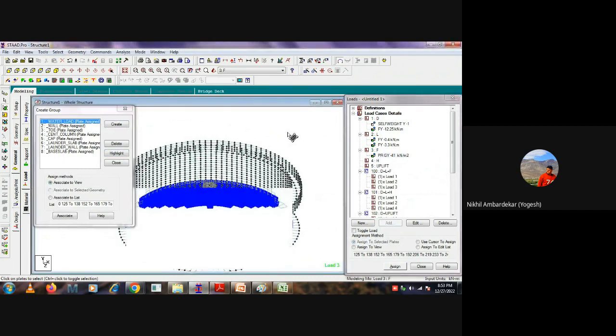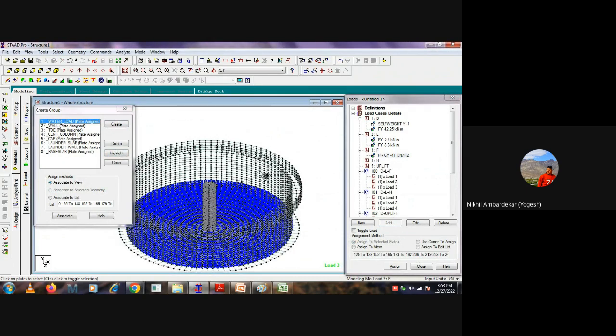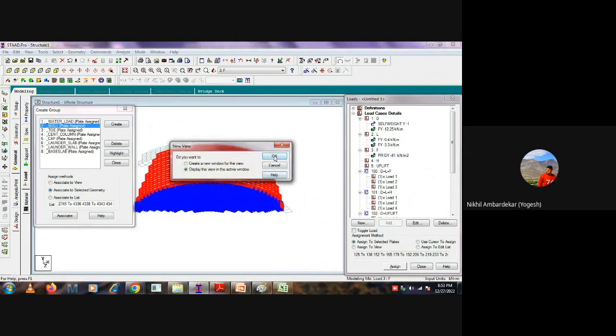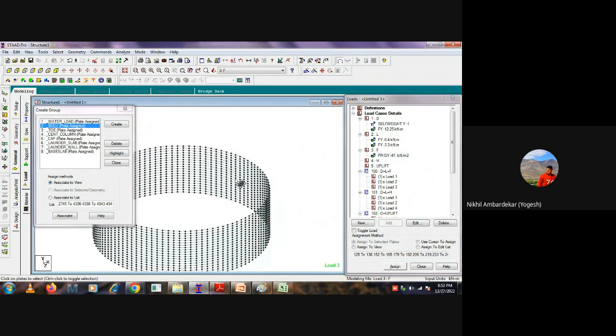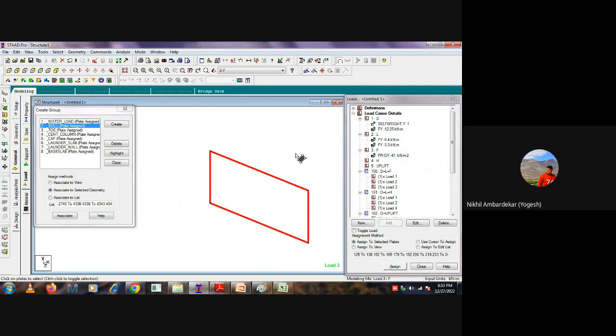Okay. Now I want to add the hydrostatic pressure to the wall. For that, I will just open the wall, highlight. I want to see the axis. Let's say this one. Control T. Okay, so local Z is outside of the plate, which means our value will be positive.